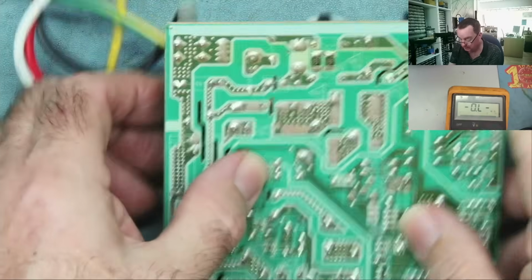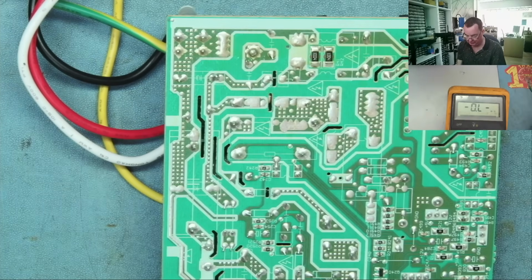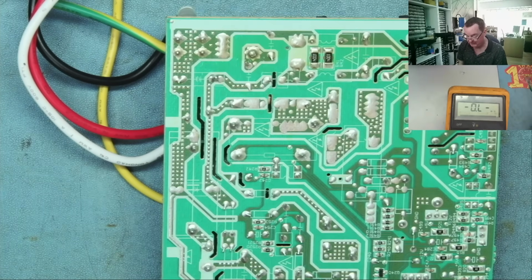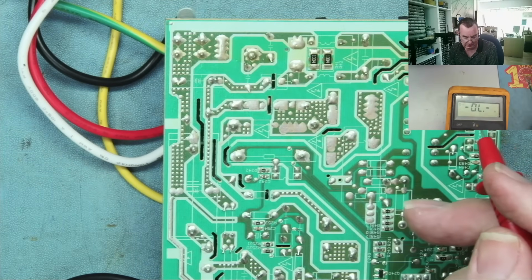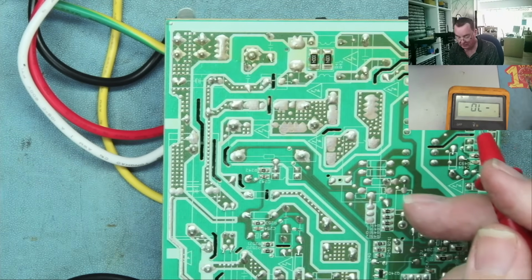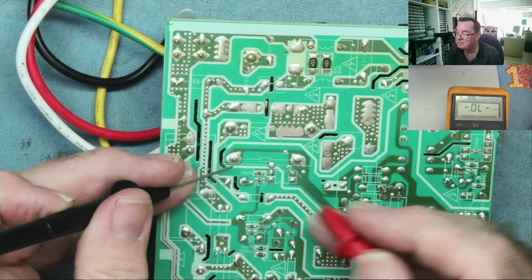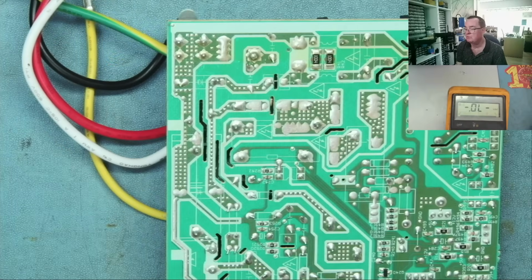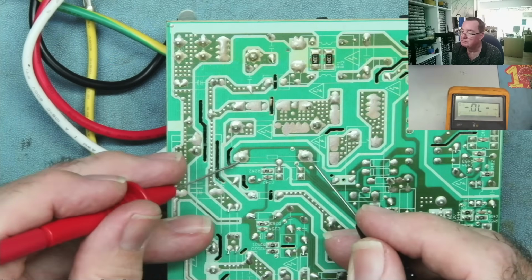This is a 12 volt relay. Okay, so we can actually apply 12 volts across here and test it, because that shouldn't harm the circuit. This would obviously be switched with 12 volts anyway. The question is the polarity. Now, the relay across the coil will have a diode to prevent back EMF, and whichever way the diode doesn't conduct effectively will tell us the positive. So let's have a look.